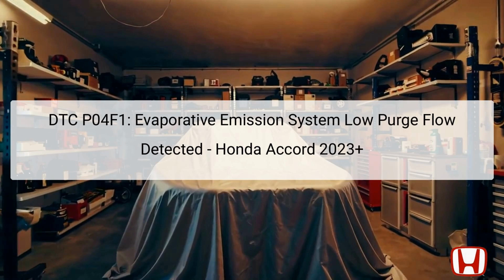The DTC P04F1 indicates an issue with the Evaporative Emission (EVAP) system in the Honda Accord 2023 or newer model. This code is triggered when the Powertrain Control Module (PCM) detects low or insufficient purge flow within the EVAP system, which can lead to a failure to manage fuel vapors correctly. The components affected include the EVAP canister purge valve, the fuel tank, the FTP (fuel tank pressure) sensor, the EVAP canister itself, and the vent shut valve.